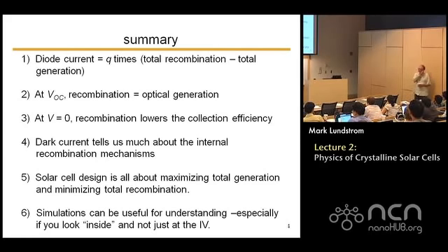So don't just look at the computed IV characteristics when you run a simulation. Look inside at recombination rates and carrier profiles and energy band diagrams and see if you can figure out how to make the device better.